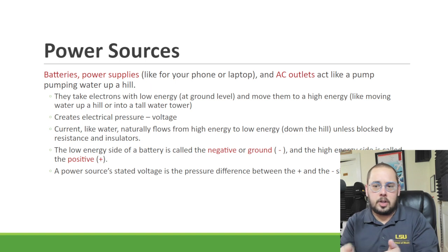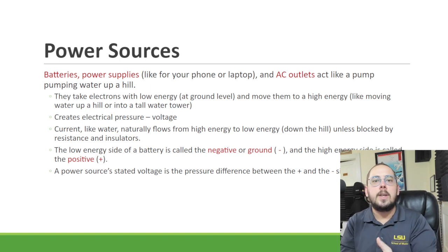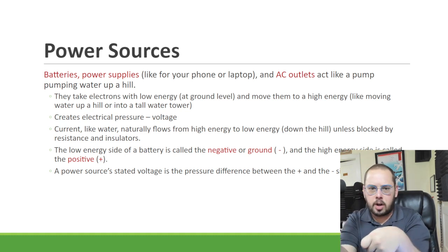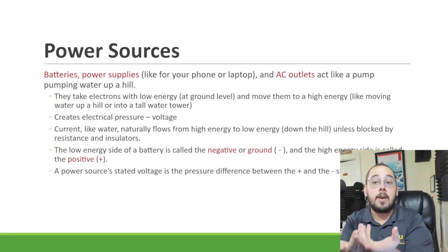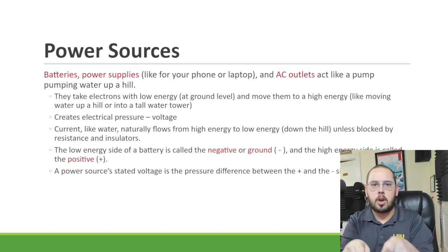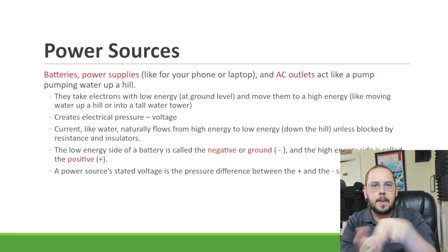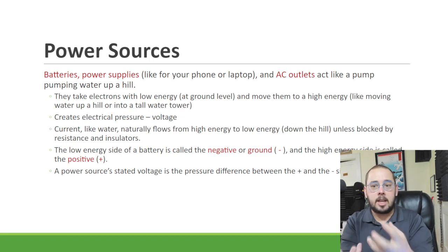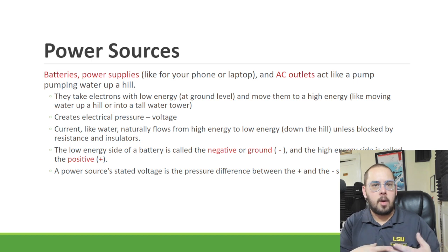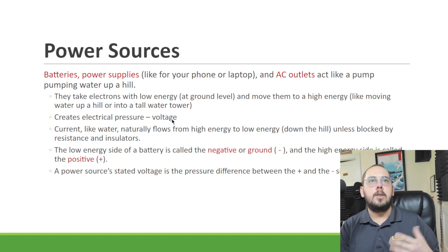And if you're still learning what you're doing, which is what you as a student in this class are, you don't go plugging in and making circuits and short. You could actually accidentally very drastically hurt yourself using the voltage coming out of the wall as you're building your circuits. And if you accidentally get something backwards, it could pop and blow up. You could short it out, or you could touch a thing and get really badly shocked. So you want to use these power sources that are a much lower amount of current and voltage. So again, using things like the USB port, that's what we want.